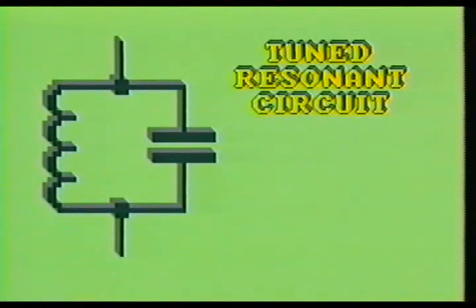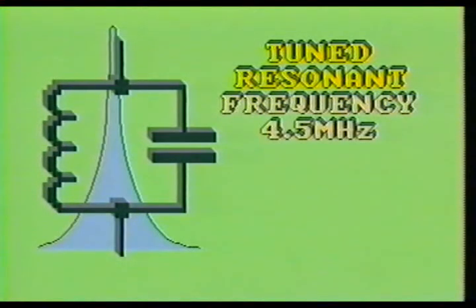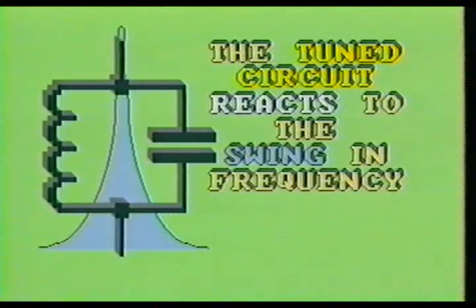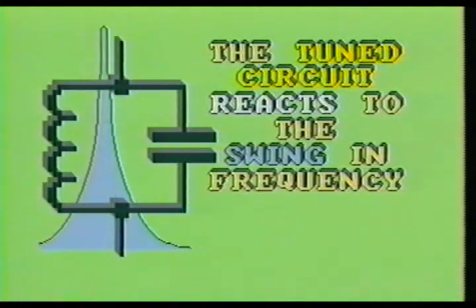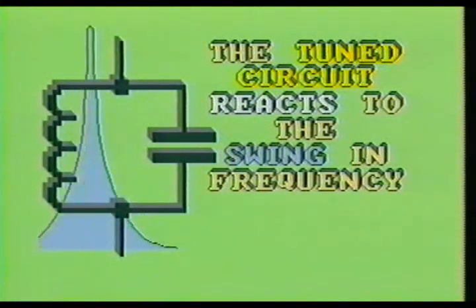The sound detector stage itself is a tuned resonant circuit. The frequency of this tuned circuit will be the center frequency of its input signal. In this case, the center frequency is exactly 4.5 MHz. The reactance of the sound detector circuit will change when the input signal swings or deviates from the circuit's tuned resonant frequency.